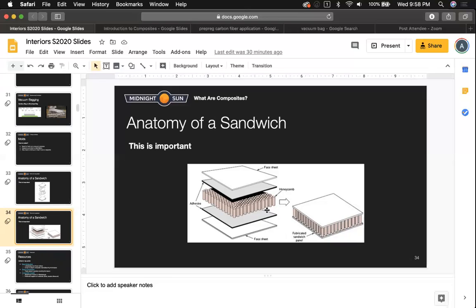A really good example of this is corrugated cardboard, where you have layers of cardboard-like paper on either side of this grid shape core. It's way stiffer than just peeling off the outsides and flexing them. They're essentially just paper. The reason for this is, if you're bending it downwards, you're loading the top surface in tension and the bottom surface in compression. And the further out you space these layers, the stiffer it will get.